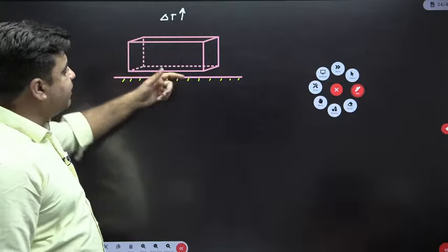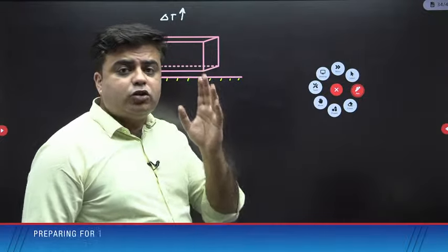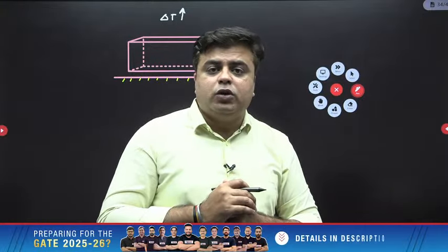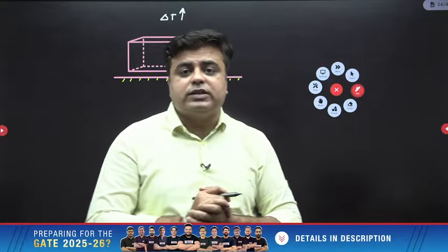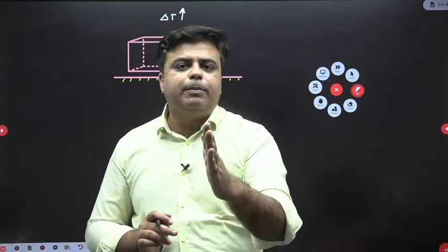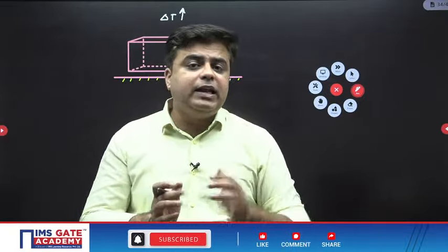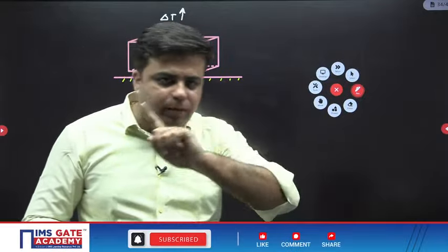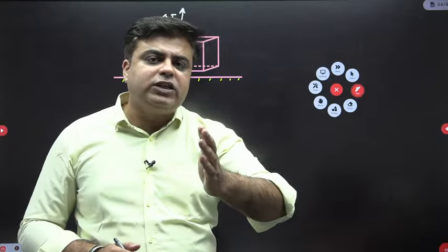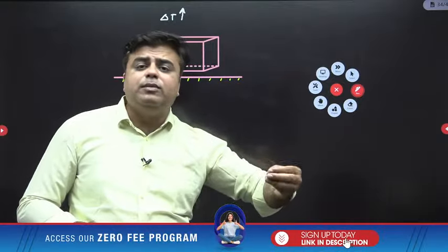If you decrease the temperature, this bar will undergo free contraction because nobody is stopping the bar from contracting when the temperature is reduced. So this is the beauty of thermal stresses. Thermal stresses will only be induced if you restrict the bar from free expansion or free contraction. If the material is allowed to expand freely, there will be no thermal stresses. But if the material is restrained along any one direction, or along 2-3 directions, then thermal stresses will be induced in the bar.